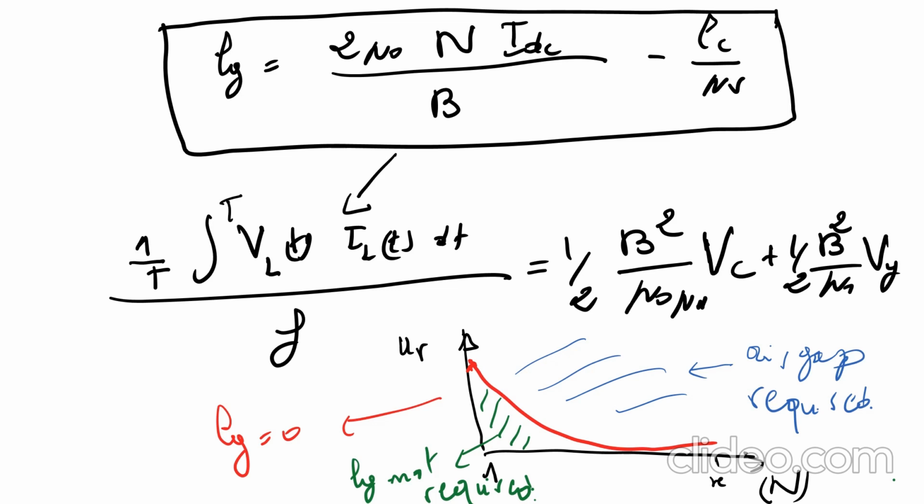if you look at any catalog of a vendor of magnetic components, you will see that they have different series of inductors, and for every series they use the same core and the same number of turns. In a few cases they change the number of turns, but in most cases they keep the same number of turns, and the DC current of those inductors is also the same, but you see different values of inductance, multiple ones.